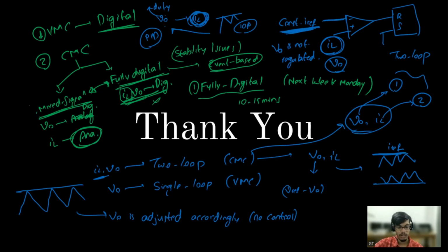Okay. Sir, one more thing I want to know is how the PID controller gives the control voltage when we feed it with an error voltage. So as I have discussed, say this is the PID controller Gc(s) in analog domain. This is Verror(s). So we have this equation, right? Kp plus Ki by s plus Kd s. This into Verror(s) gives me Vcontrol(s). So accordingly, it will be decided.